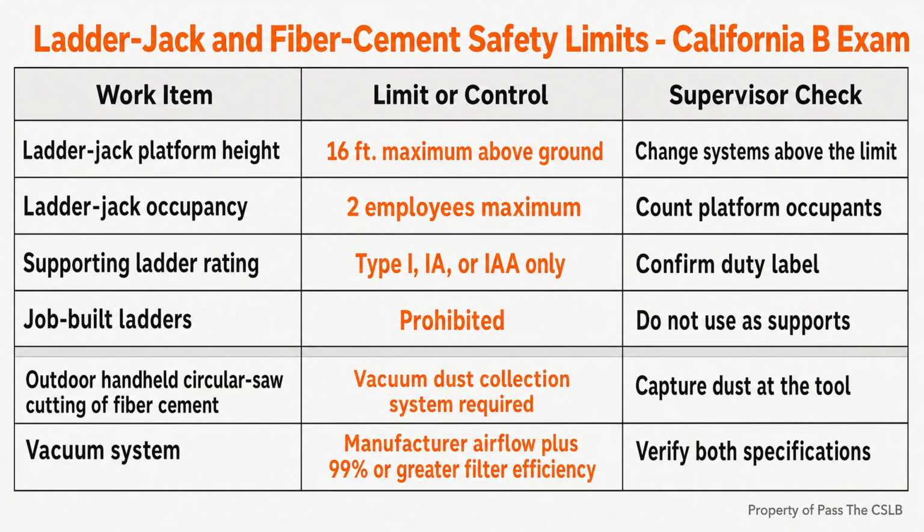During fastening, I separate length from face condition. Vinyl fasteners need at least 1 1/4 inches of penetration into the sheathing and framing combined, with the through-sheathing condition handled as specified. Wood siding fasteners need at least 1 1/2 inches into studs and sheathing combined or blocking.